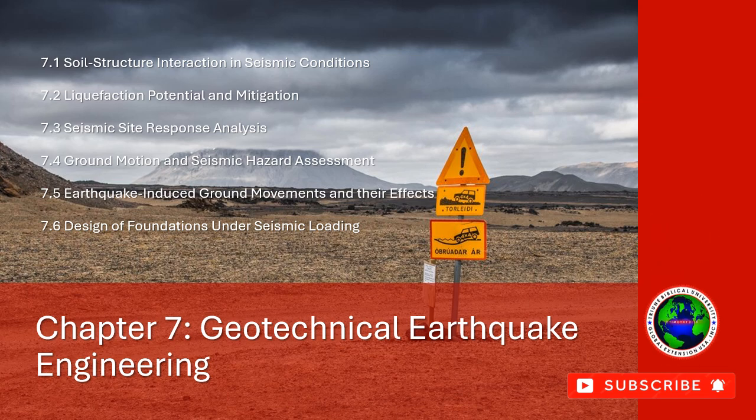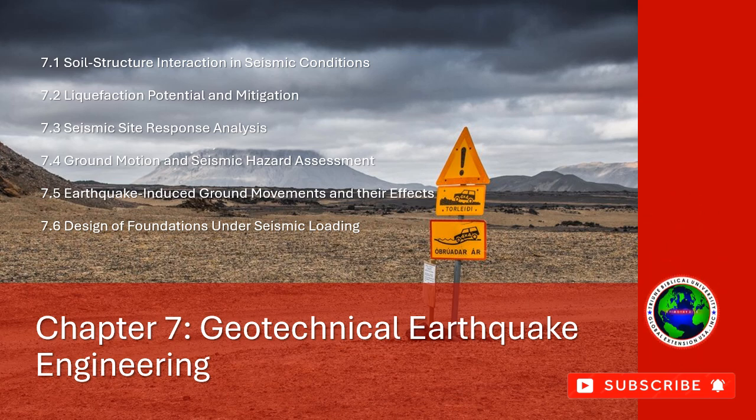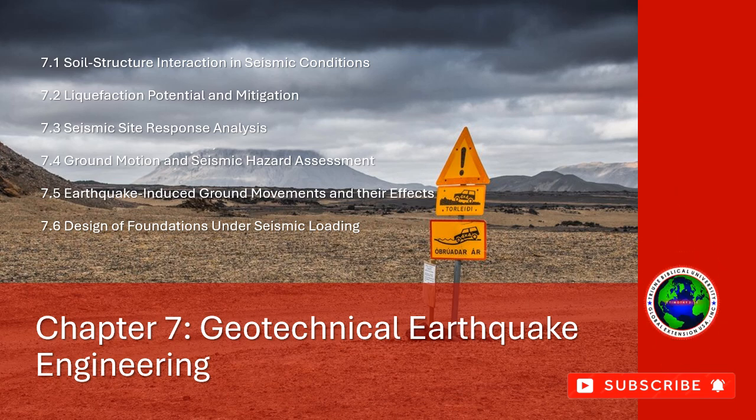2. Cone Penetration Test (CPT). The CPT involves pushing a cone-shaped probe into the ground and measuring the resistance to penetration, the tip resistance and sleeve friction. Data obtained from the test are used to evaluate soil properties and the likelihood of liquefaction. The CPT is often preferred over SPT for its continuous measurement and more accurate profiling.